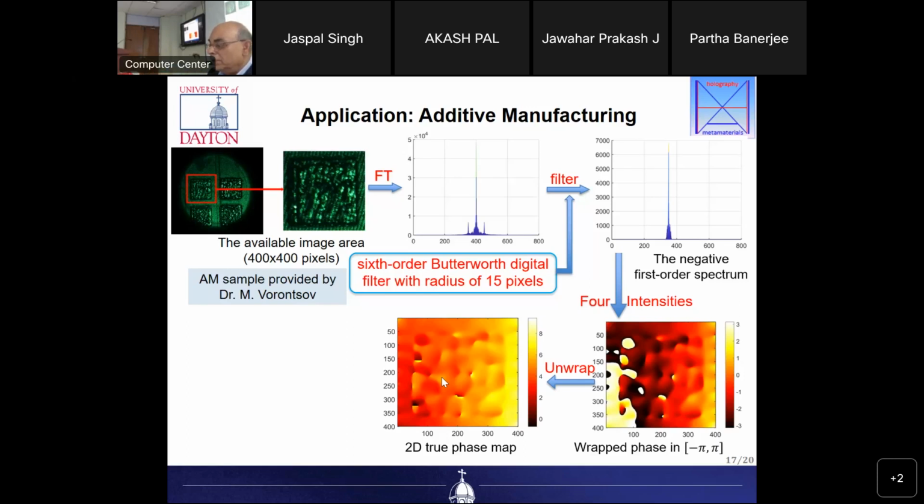And what is important in this is actually what kind of laser pattern you need to melt that metal. That's where the art is. We didn't do that, of course. So you have to have a certain laser with a certain cross section, or you have to design some diffractive optic element to make a certain cross section so that the laser effectively melts the metal so that it can freeze immediately after. Okay, and as it turns out, there was a whole bunch of people working on this. The laser beam has to have some kind of a cross shape for whatever reason. I mean, that all comes from metallurgy, of course, and material science. So this is an application.